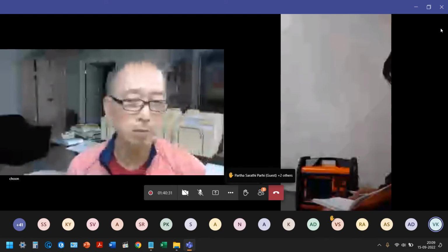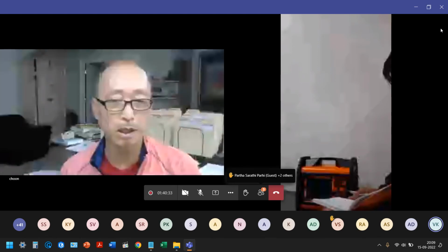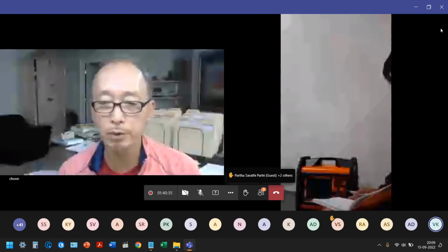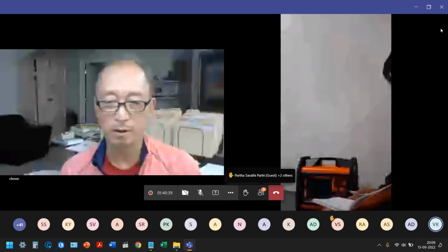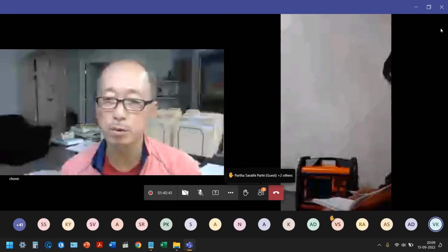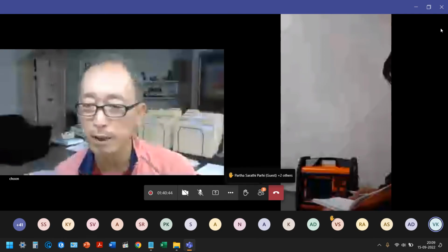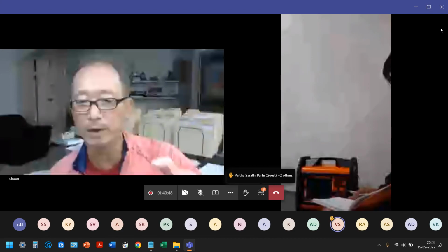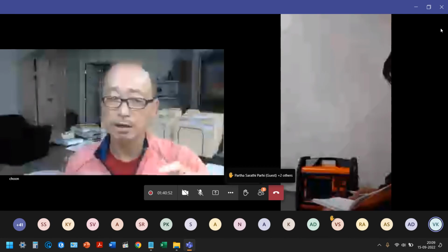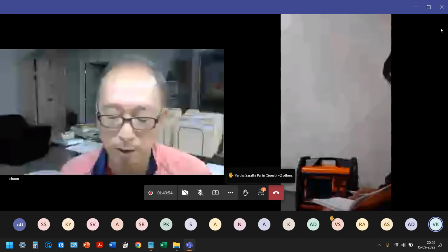For increasing resolution in the top layer, what will be the typical receiver spacing? To increase resolution in the top layer, you have to shorten your receiver spacing. In other words, you should not use too long a receiver array to cover your depth. For example, if you want to cover only the top 5 meter depth range, then your receiver array length should not be longer than 10 meters.